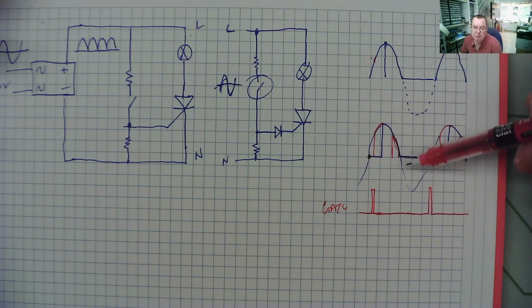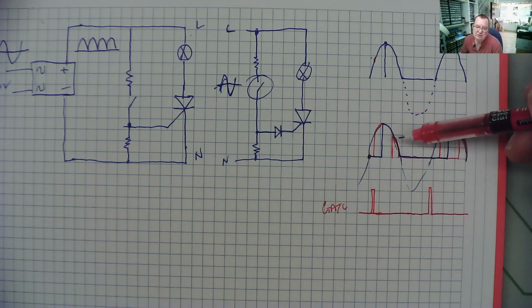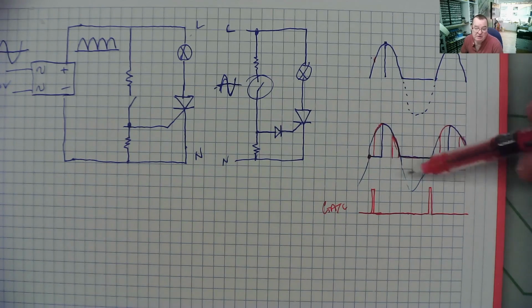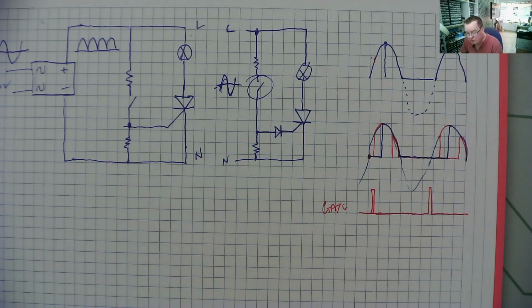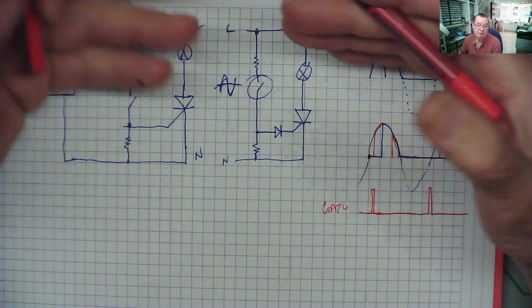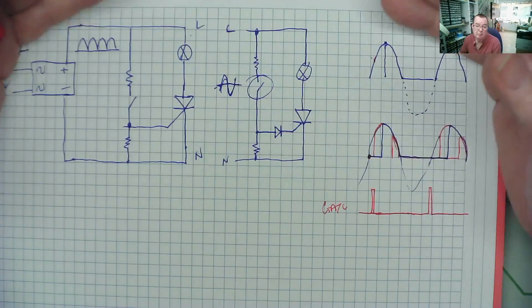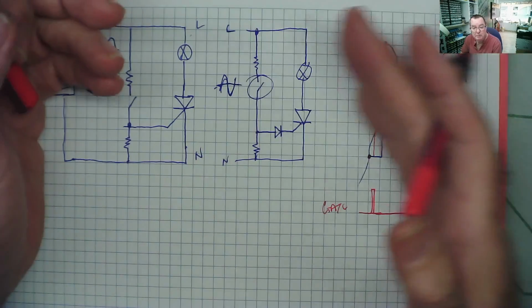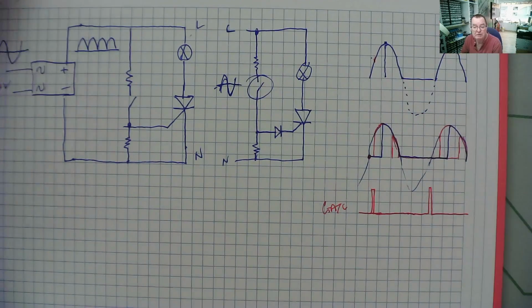It's the natural behaviour of the thyristor to switch off when the main current stops flowing that eventually switches it back off again. Okay, so it's not really pulse width modulation, but you can vary the output. For example, you can make the light bulb dimmer or brighter just by moving the position of the pulse in relation to the 0 crossing point.